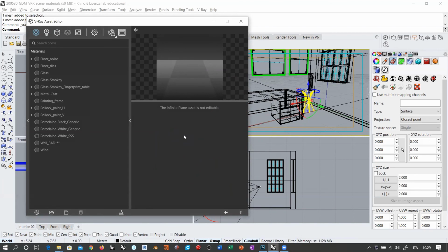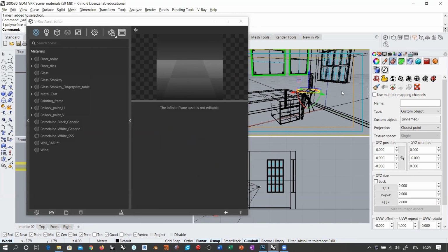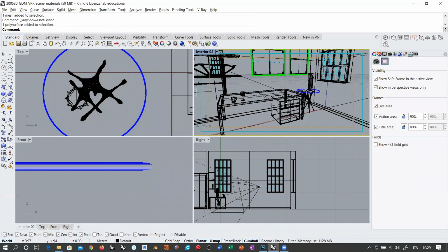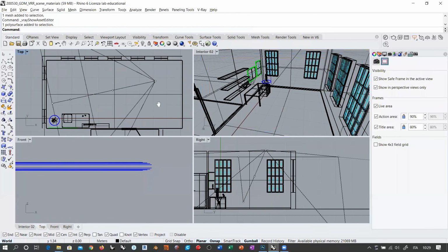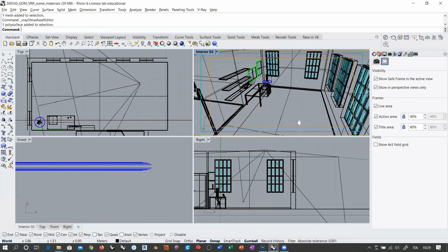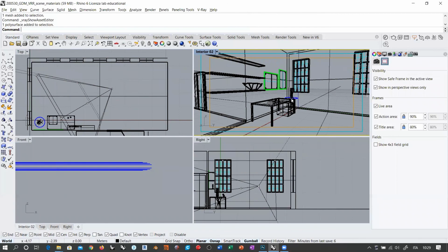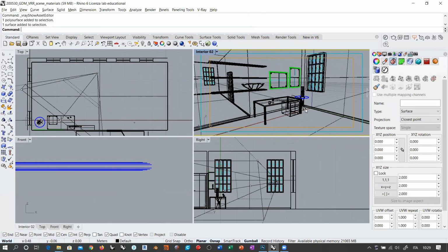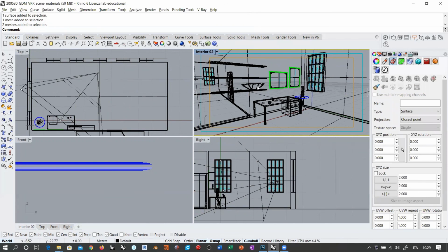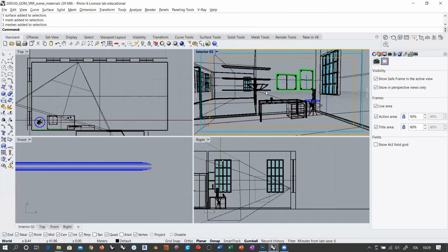Unwrapping is the best thing that you can do if you want to create some complex texture mapping. So unwrapping this cylinder was very easy, but unwrapping complex things is complex. Normally, for example, imagine unwrapping a tree. So the trunk, the branches, and so on. So that's already somehow more complex. Without reaching this kind of complexity like the legs of this table or this object here, this is going to be quite a mess. So in this case, if you looked at this from the distance, you could use triplanar texture.